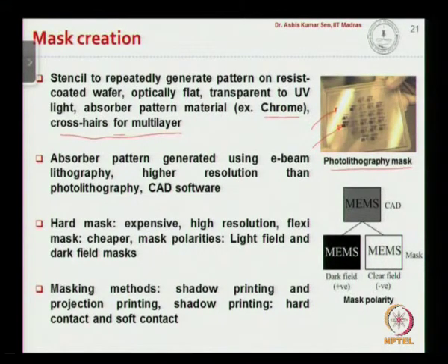Now, to create these opaque patterns, we use what is called e-beam lithography. Okay. So, we use the mask for photolithography, but to create the structure or the pattern that is used in photolithography, we use a more sophisticated technique called e-beam lithography, which has higher resolution than the photolithography. Okay. And this is possible because we have the design of the mask. So, using a CAD software, it can be converted, and we can ask the e-beam writer to write the mask on a specific material.